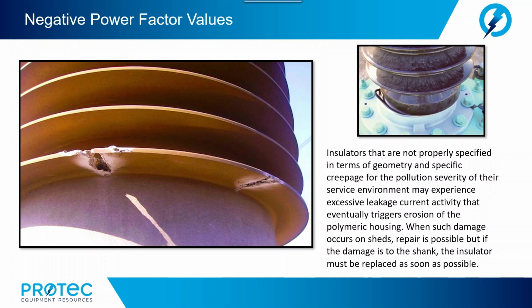This condition is most likely to arise when making ungrounded specimen tests and grounded specimen test measurements on specimens who have a capacitance value of a few hundred picofarad or less. Equipment such as bushings, circuit breakers, and low loss surge arresters will fall into this category.